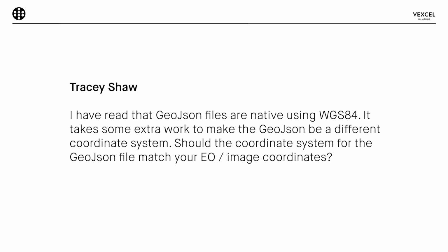Yeah, so very important point. The files that you import need to match your EO, the exterior orientation, and the image coordinates. Well, the image coordinates are in pixel units in the image system anyway, but all the coordinates which are in the world coordinate system need to match. So that is true for the ground control points, for the GPS data, for the map sheet files, any other data that you combine throughout the UltraMap workflow.